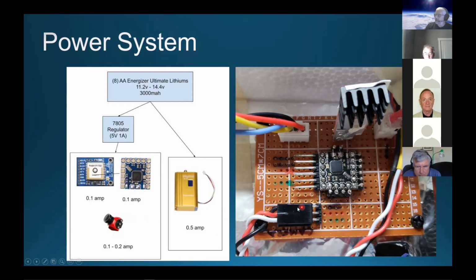So here's a little board I whacked together. So we were taking, I believe this cable ran off to the batteries and pumped that power right back out. This is the cable, this cable here on the FPV transmitter. Put a socket on the board for that. The on-screen display module, which runs off 5 volts, sends it off to the GPS. So this cable runs to our GPS and is fed 5 volts. And this cable leads to the FPV camera, which runs 5 volts. And I put all these special connectors right on this board so I didn't have to do a whole lot of surgery on my devices, just use the cables they came with. Nice thing about having a deep parts bin. So that was a little custom board I built for the power and routing of the video.